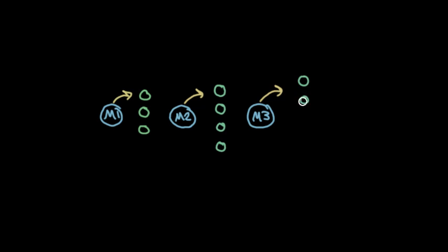That's not the only way to do it though. Instead, you can make it so machine 1 works on all their widgets and just kind of piles them up here as machine 1 completes them. And machine 2 does the same thing, and so does machine 3. And depending on the rate of the machine kind of determines how many different widgets you have sitting at the end of the machine. And these little sets of work in progress, or WIP, that kind of set is called a queue.